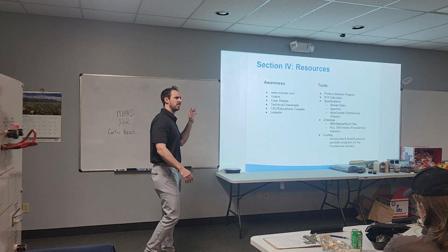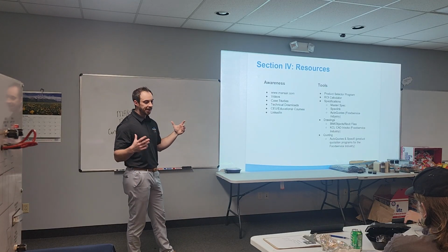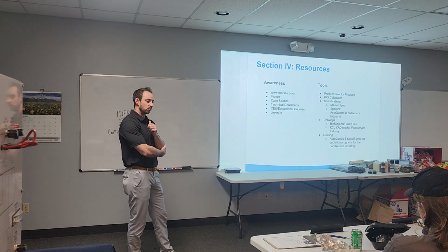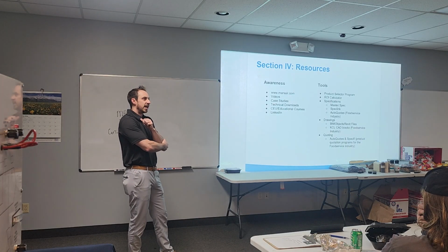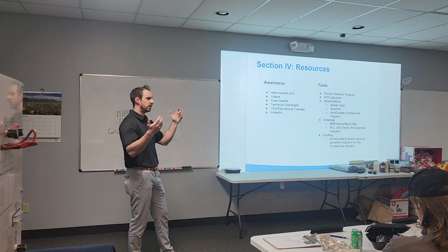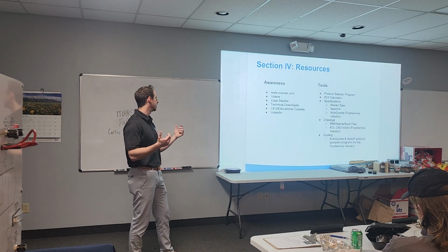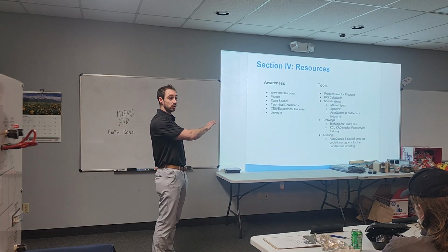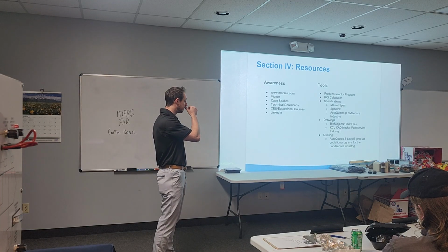I think we've got maybe a dozen videos on the YouTube channel now. I'd say all of them are 5 minutes or less. They're really good ways to get comfortable with troubleshooting and servicing the units. Some of them are how to swap out our motor fan assemblies, how to reset thermal overloads, just the various things. We started with the most common issues that happen with the air curtains.